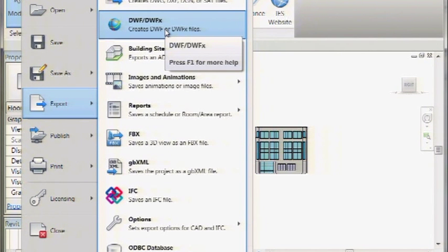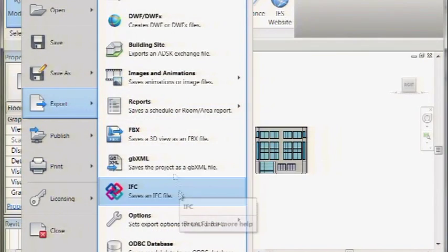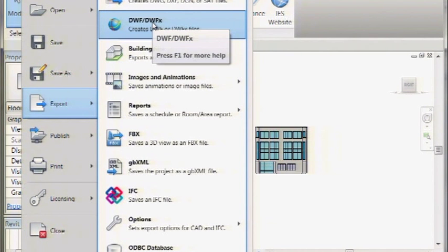if I want to trace that image. And there's actually a good video on our website that shows how to take a 2D DXF and trace it onto a shell and then stamp it onto your building. You basically draw it on an adjacent space and then put it adjacent to your rooms. It kind of stamps it on there, then you delete the space. So if you want to just take the facade, that would probably be the quickest way. But remember that you always have this option too to take out DXFs.